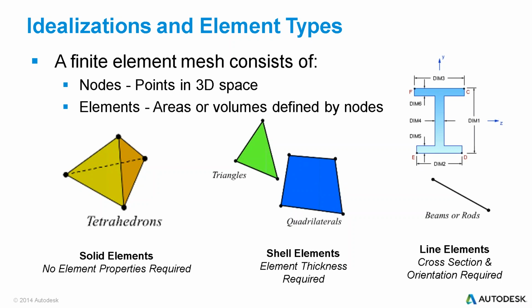Then of course with the line elements, simplified structural analysis, if you're building a 20-story building, you're probably not too concerned with how the flanges might deflect under a certain amount of stress. You're more worried about the overall I-beam. So when you're working with something that large, like a 20-story building, simplifying it to a beam or a rod type element with connector points, you get the results faster.